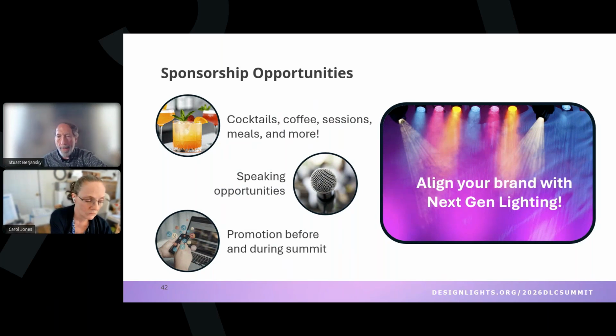And the question is, for DALI drivers, is there any reason why a manufacturer developing a new DALI driver would launch DALI 2 and not D4i? Well, it's a good question. So DALI 2 is technically everything that is after the beginning of the certification. DALI 2 marks the beginning of the testing program. So D4i is also DALI 2, but we need to distinguish between them because they have different features and capabilities, different architectures.